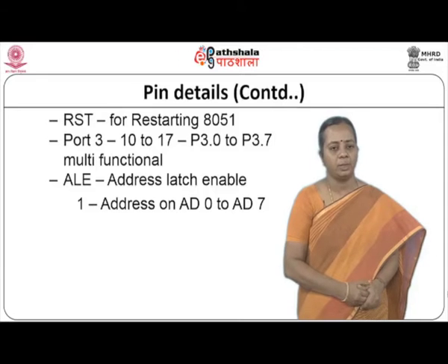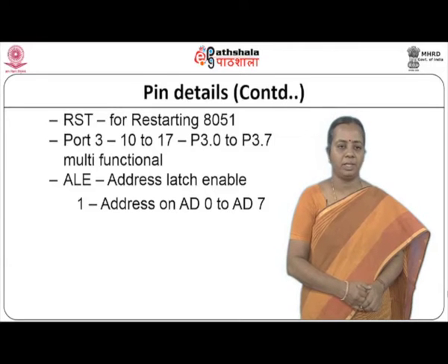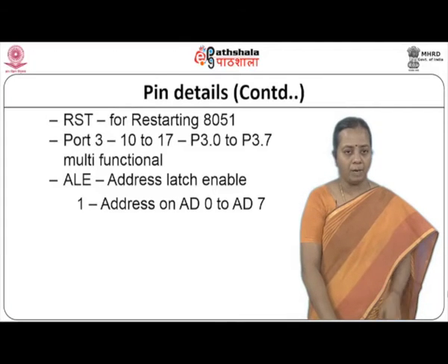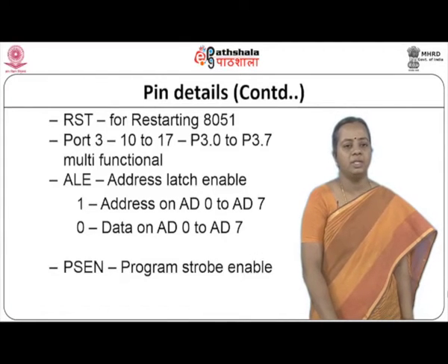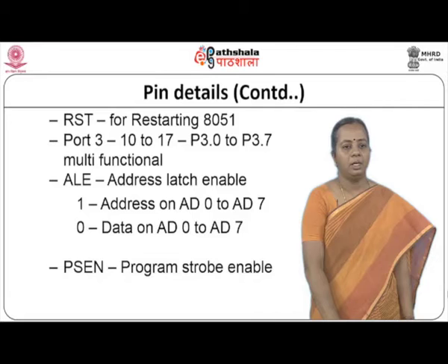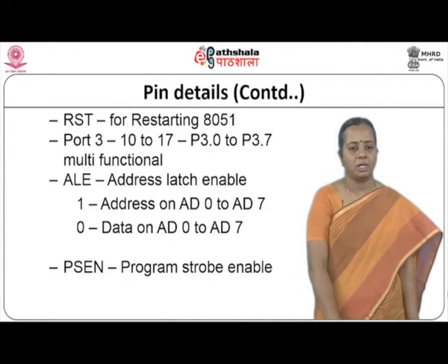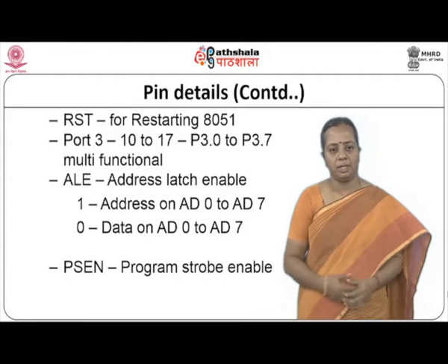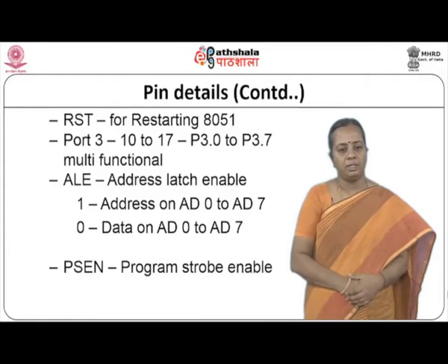If something happens, we can restart the 8051, and for that they have given that particular pin. We also have port 3, which is available from pin number 10 to 17. This port 3 is a very special port where each pin has multiple functions. We will see that in detail in the next slides. Maybe the other things we will cover now.